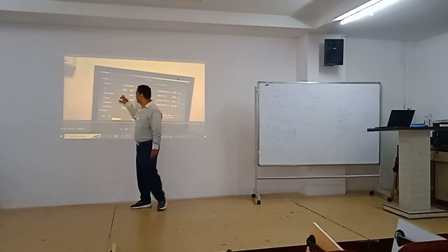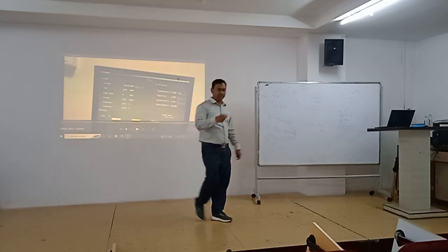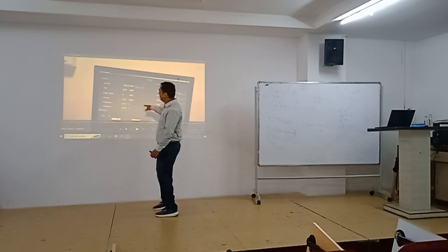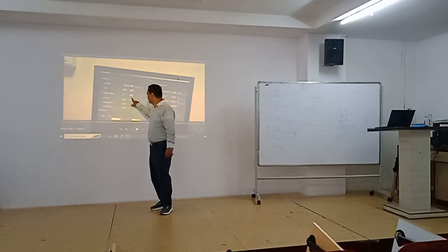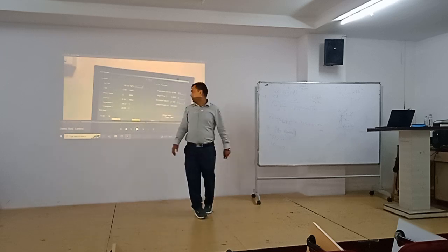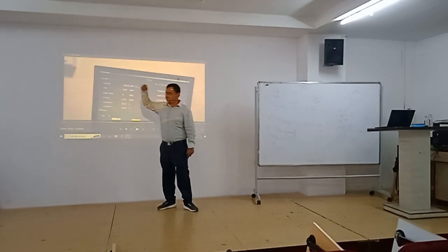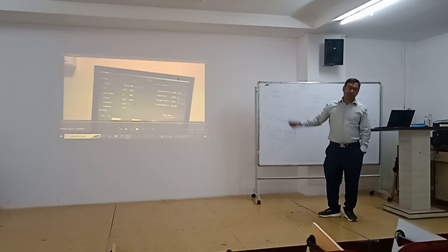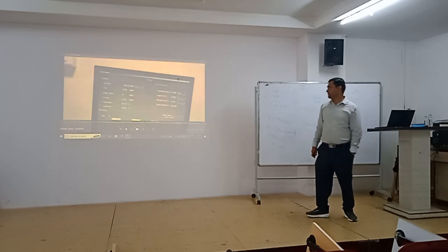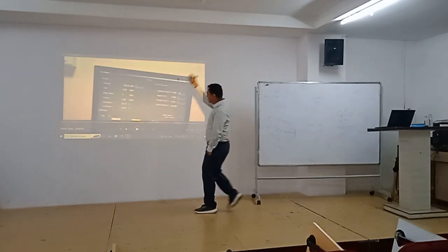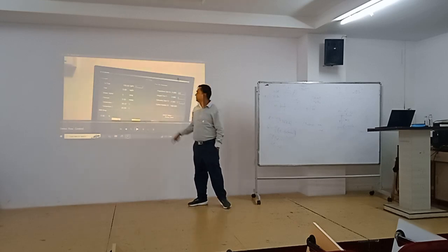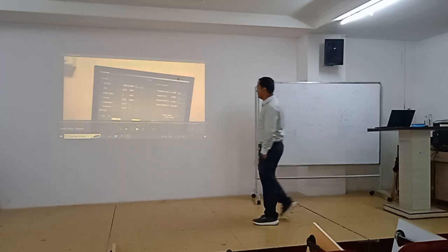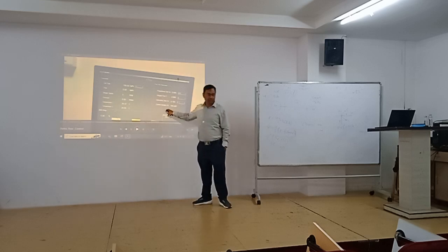This will display the motor speed. Then the pressure in the pipe. We definitely need to measure this pressure also, because sometimes if pressure increases, the pipe may burst. Then we have temperature 1 and temperature 2. We put two temperature sensors there, and afterwards I'll show you. They are measuring the temperatures. This entire control we are doing by setting the PID gains, that is Kp, Ti and Td. C means control value.